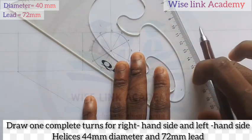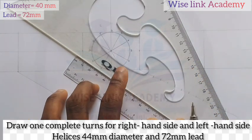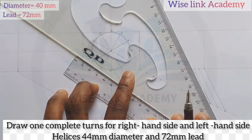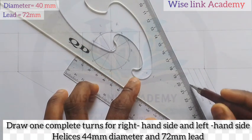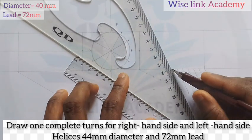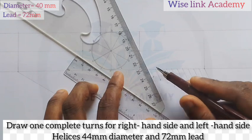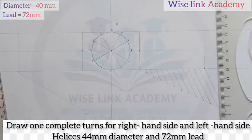After connecting it down, I will hold it down. I will take my meter rule at this edge here, right? So I will slide on it this way, to the next point, to the next point, and the next points, and also my last point. I have this. So I have divided this circle into 12 equal parts.